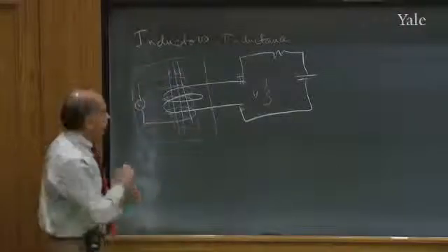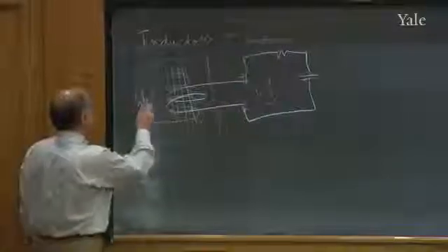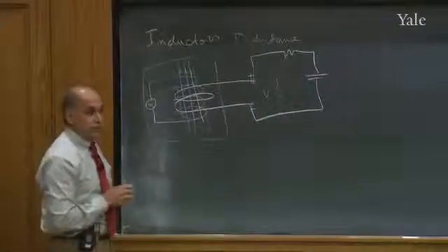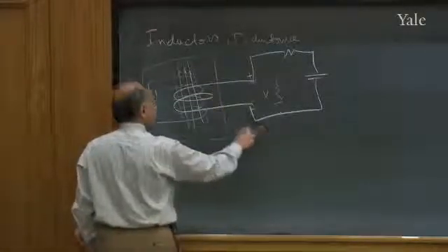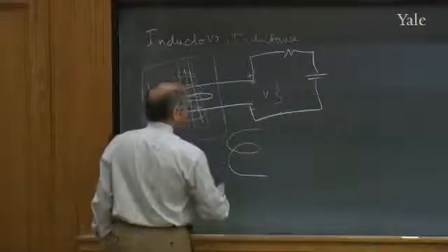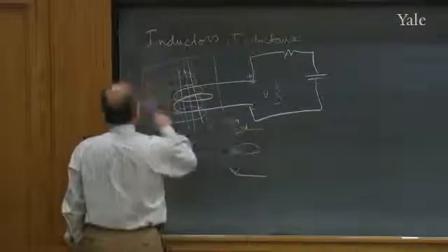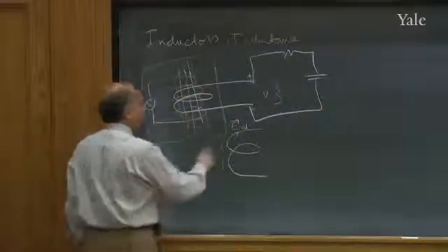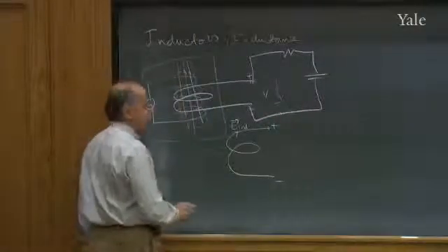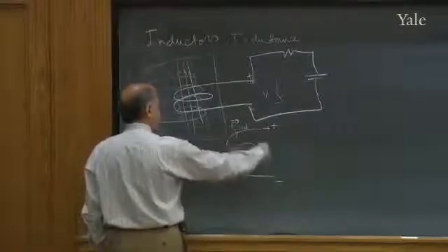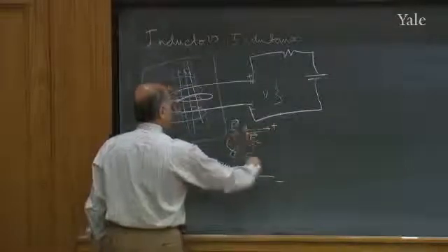If it never bothered you, you can ignore this part. But it's important to understand how we can have a notion of a voltage in the presence of time-dependent magnetic fields, because the line integral of E is not 0. Once again, what happens is, if you look at this coil, there may be an electric field that is induced now due to the changing flux of that. They'll try to build up charges here and take them out of this end. After a while, these guys will say enough, and they'll start fighting you till they set up an electrostatic field, a Coulomb field, inside the wire that cancels this.